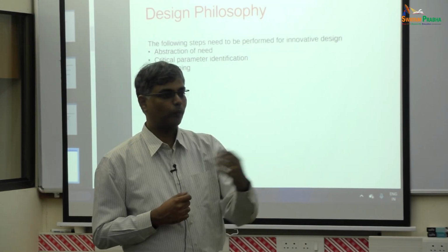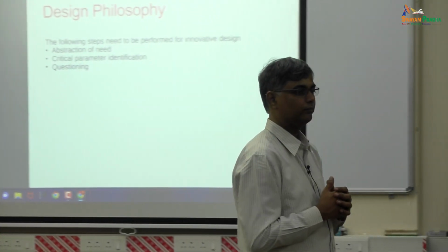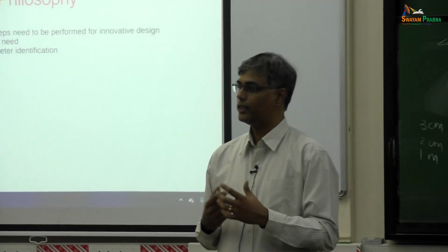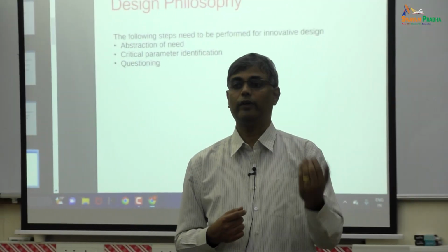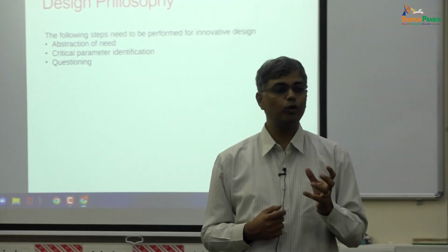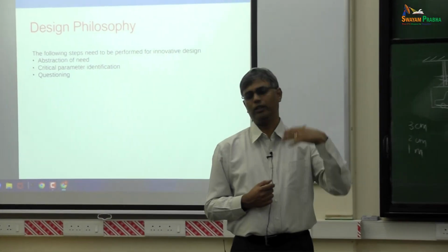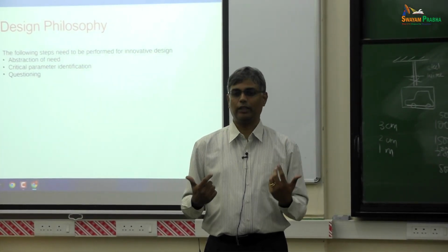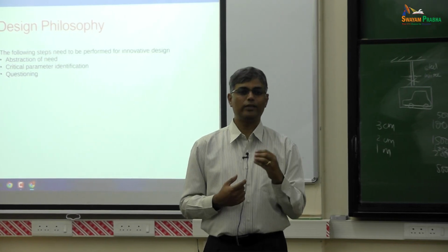Okay, so question? Yes, how exactly are we considering a bridge to be statically loaded? Because we have traffic going over it, especially in peak hours, it could increase a lot. Okay, so his question is about the bridge which I said is statically loaded, and he's worried about whether there's also dynamic loading on the bridge. It's just the ratio of the static load to the dynamic load. The dynamic load component will be very small for these sort of structural objects compared to the static load.